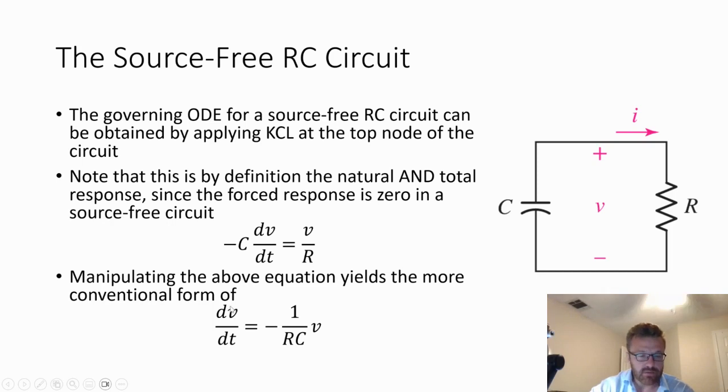What I see is that the solution to the circuit is such that the rate of change of the voltage with respect to time is simply proportional to the actual voltage itself. So you know a function that exhibits that type of behavior, namely exponential functions. When you take the derivative with respect to time, you just get the individual function back. The exponential function is called an eigenfunction of the first order derivative operator, which just basically means, for those of you that have seen linear algebra with eigenvectors, when you place them into an operator, the individual input is maintained.